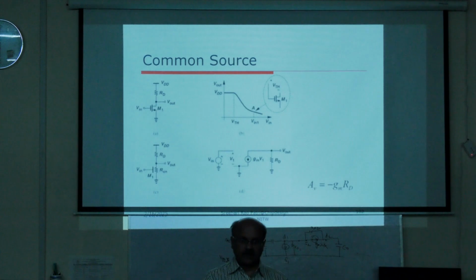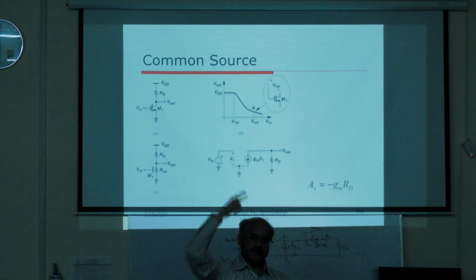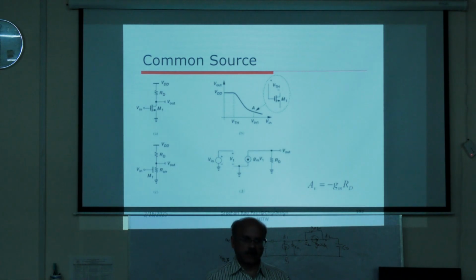So the gain is 2500, whatever gain is given to you, and you know the gain is equal to A1 into (1 plus A2), right? Assuming that A2 is equal to A1, the GM and R naught are the same for both of them. A into (1 plus A), equate that and try to get what is A. Once you know A is equal to GM1 R naught 1, already GM1 you have calculated, substitute that. So you will get R naught 1.